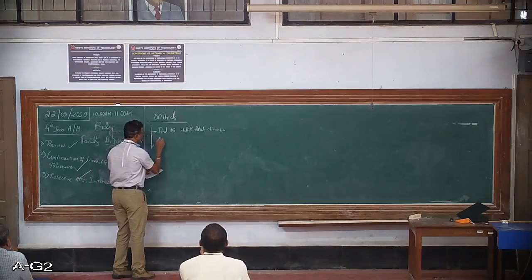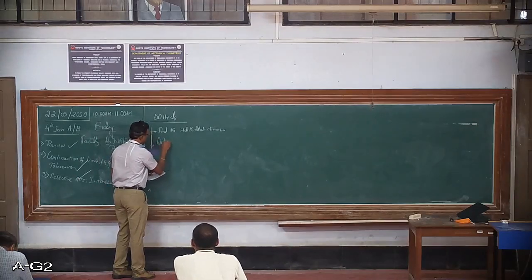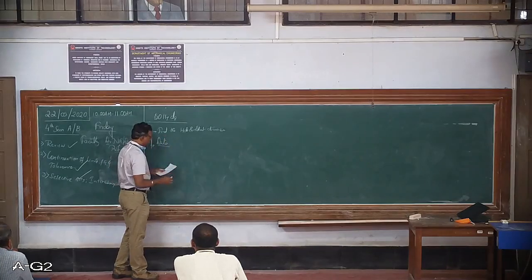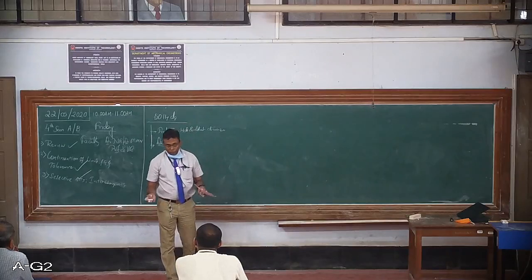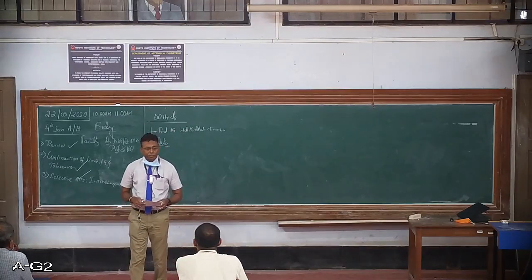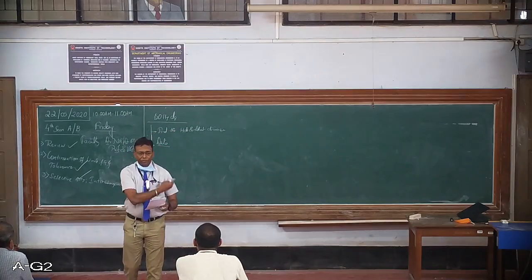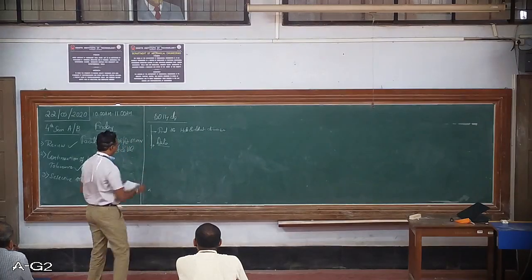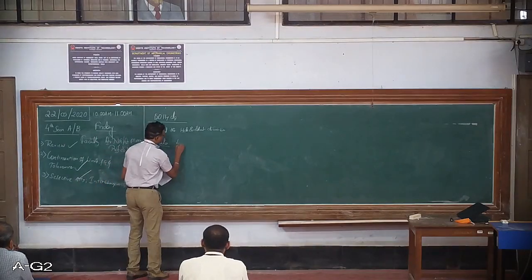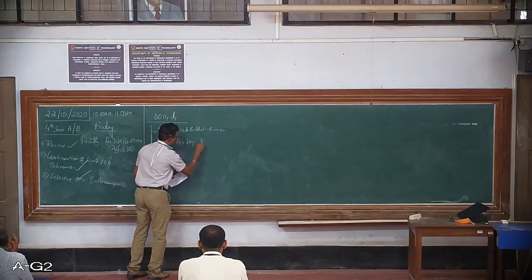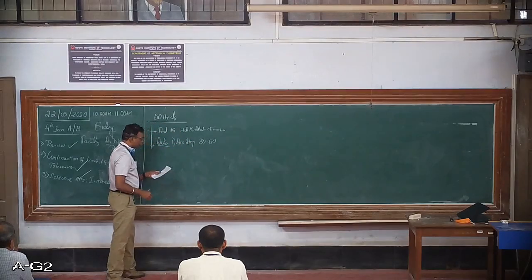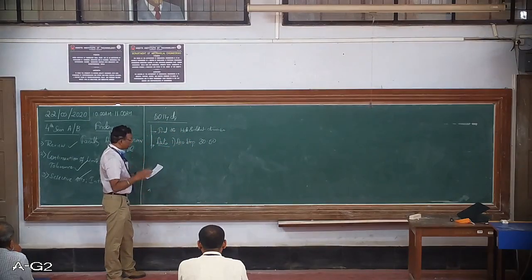The diameter step sometimes could be given, sometimes may not be. It is not certain that the diameter step would be given in the examination. Here he has provided the 30 to 50 range. This is the diameter step, 30 to 50. First information: the fundamental deviation for the D shaft has been given.